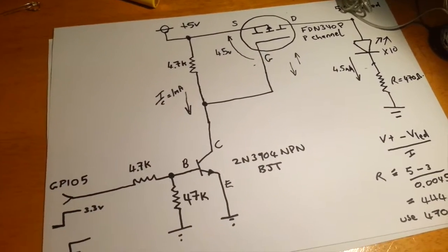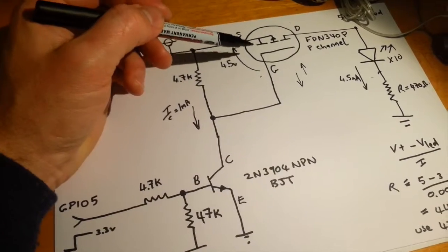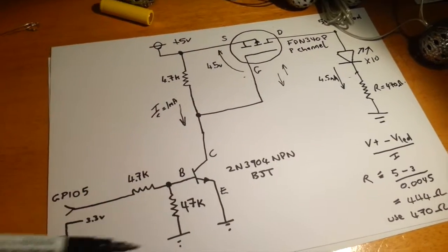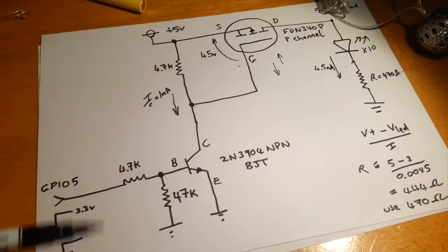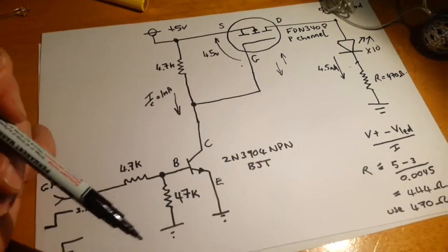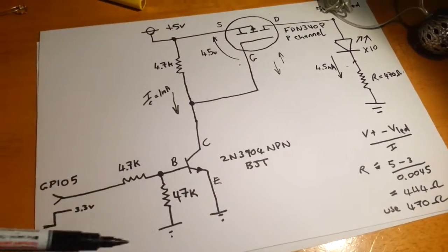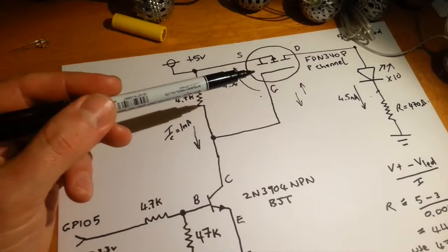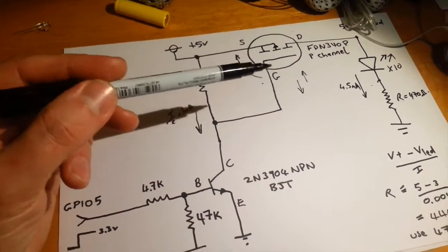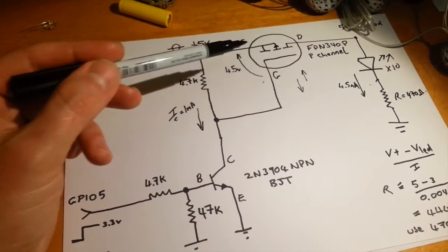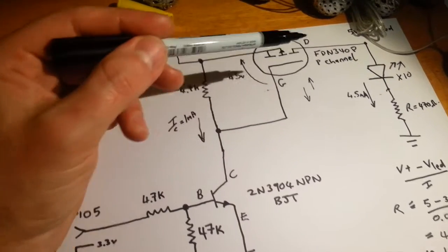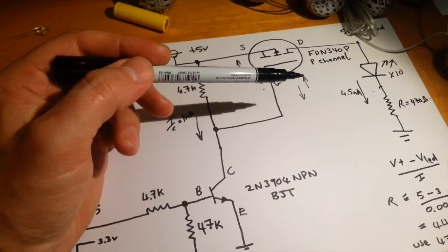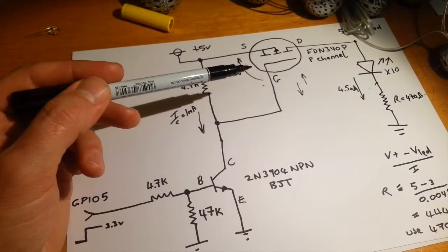So there's a few more things to be said about this circuit. The first thing is that what I've got here is a high side switch. This is quite advantageous because it allows your entire circuit to have a common ground. If you're designing a PCB for this, it's often convenient for all the grounds on the circuit to be tied together, perhaps connected together by a copper pour on the PCB layout, and then to do switching on the high side like this. So it's partially a convenience why I've gone for this approach. The other thing is that I have a P-channel MOSFET on hand that was logic level and a good fit for this application. So high side switching is what I opted for.